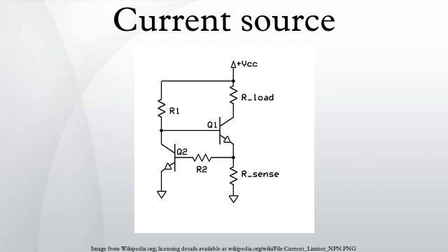Simple transistor current sources. Constant current diode. The simplest constant current source or sink is formed from one component, a JFET with its gate attached to its source. Once the drain-source voltage reaches a certain minimum value, the JFET enters saturation where current is approximately constant. This configuration is known as a constant current diode, as it behaves much like a dual to the constant voltage diode used in simple voltage sources. Due to the large variability in saturation current of JFETs, it is common to also include a source resistor which allows the current to be tuned down to a desired value.